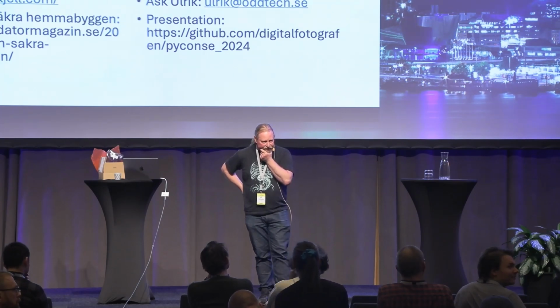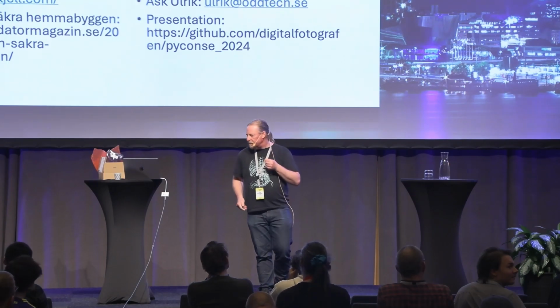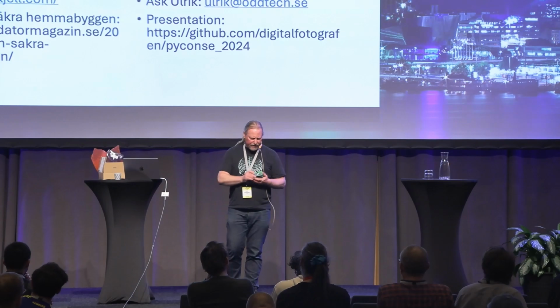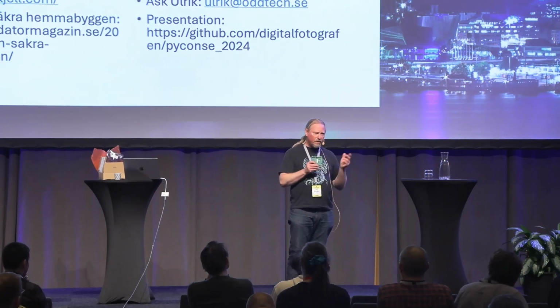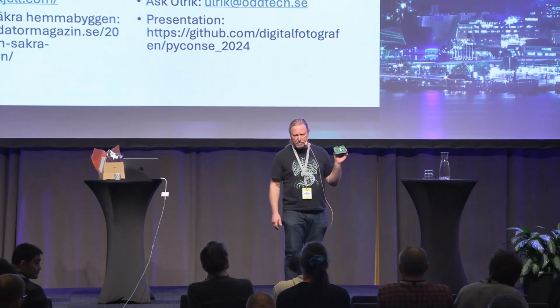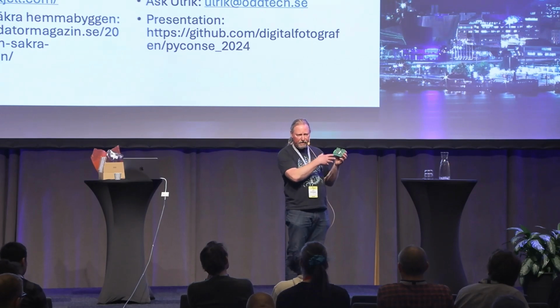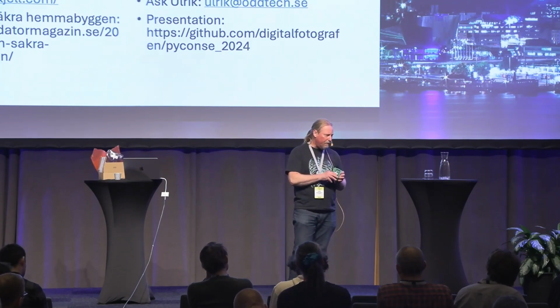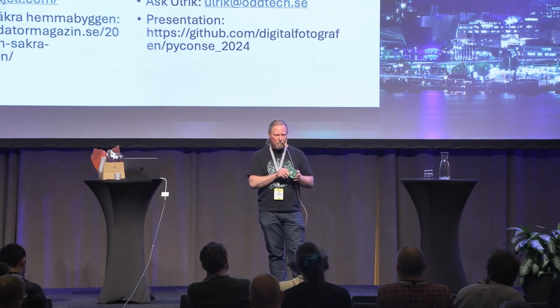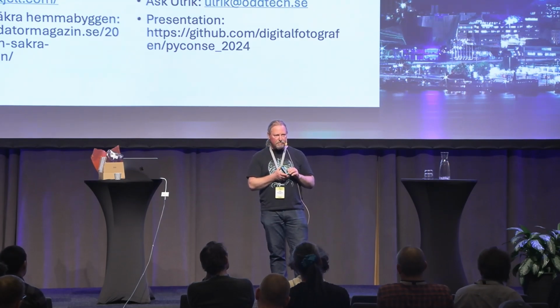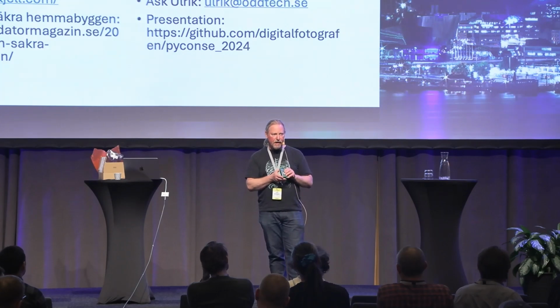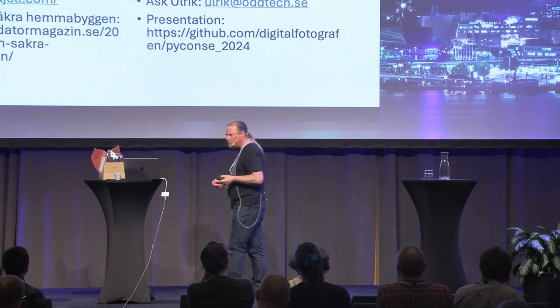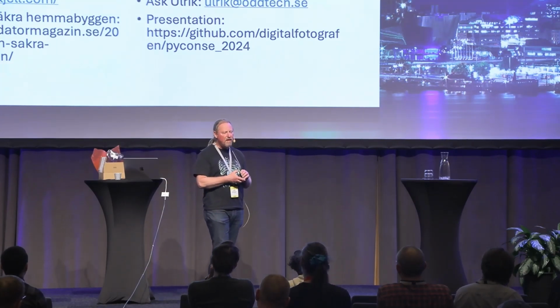And I'm curious about the Pi plates. How fast can they sample? Not really fast. If you do one channel, I think you can do about 600 samples per second. And if you use multiple channels, then it slows down. The poor thing with them is that the Python library is not very well written. I've tried to communicate with them. I've given them some hints. So we will actually start to design our own DAC cards. I'm not sure about this MCC. I haven't tried them, but I think they are faster.